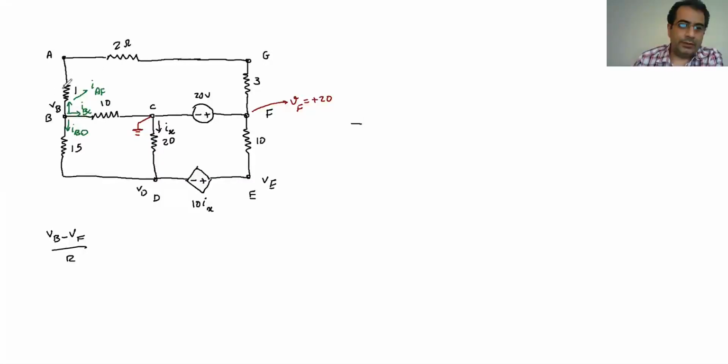One resistance, then the next one goes right after that. Then another one goes next right after that. Look at these 3, the 1, 2, and 3, these 3 are in series, because one of them goes right after another one. So I can replace that. I say, okay, this is going to look like this.